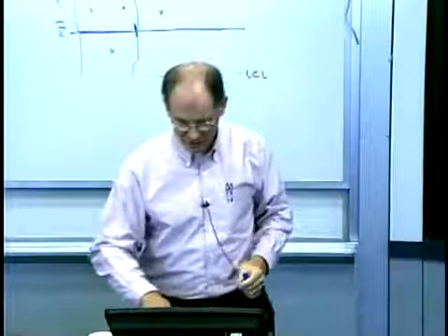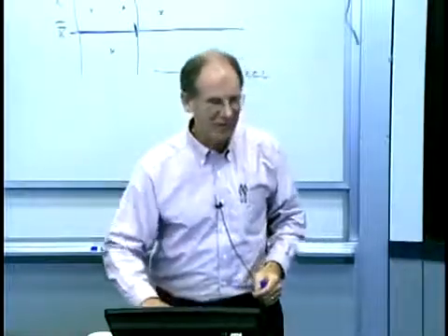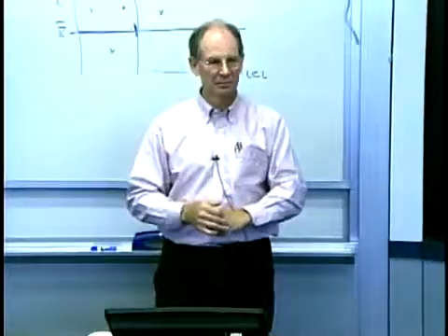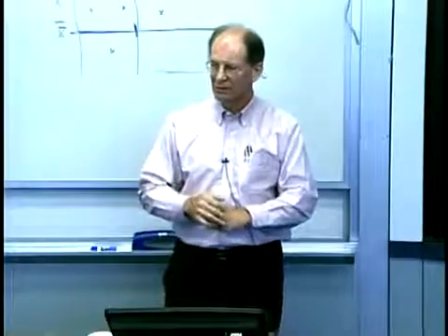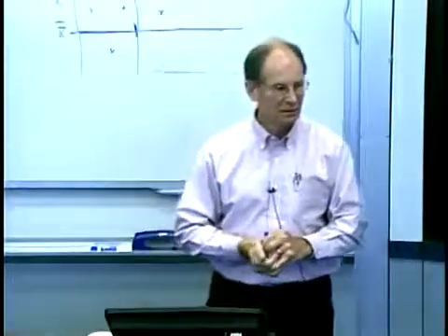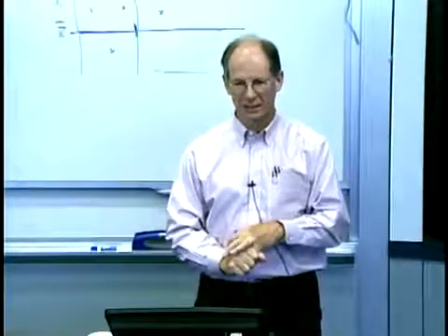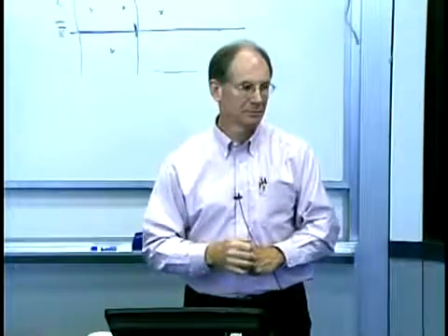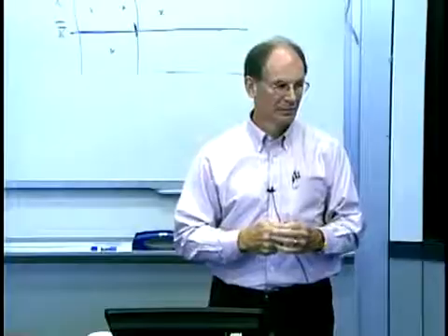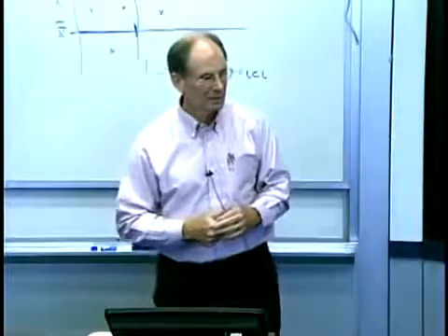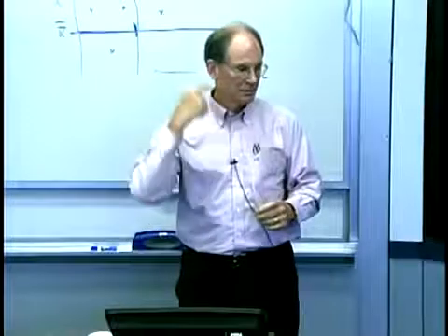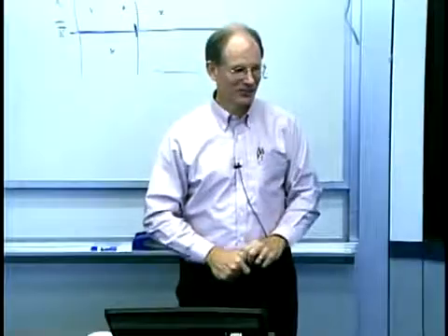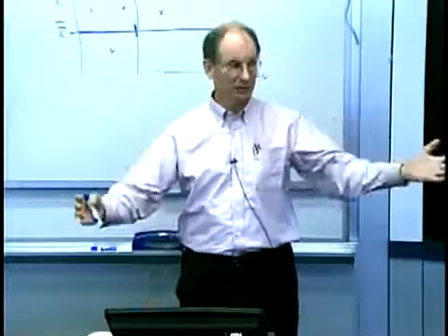But what do you do with these? How would I take these, I don't know, 25 to 50 points before I actually start doing control, and say, okay, looks good? What kind of things would you do if I were taking data to say, yep, looks like I can now apply charting? What am I looking for in the data? Probably an expected value for a dimension or something. So we could take plus minus 3 sigma from the expected value and find actual data points which are within. That could be very dangerous for a reason I'm going to show you in a second. But yeah, you have certain expectations for the process.